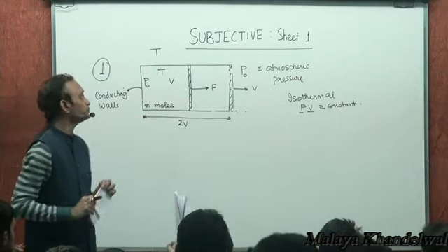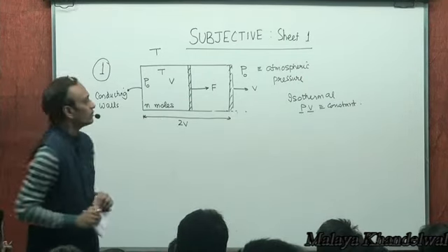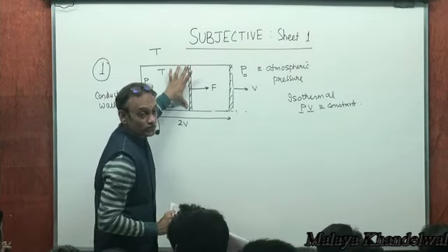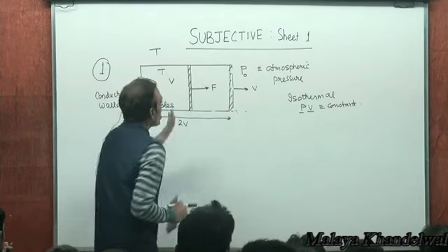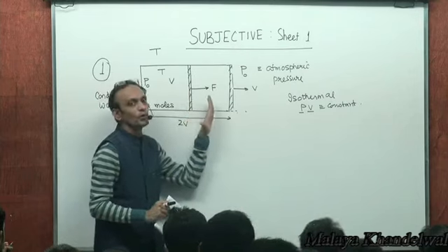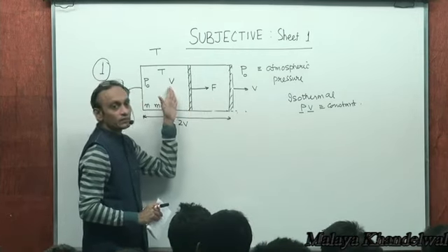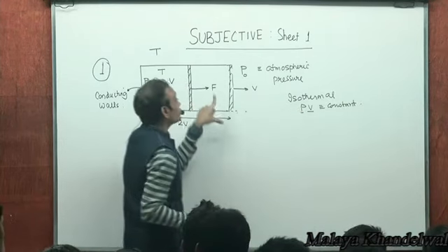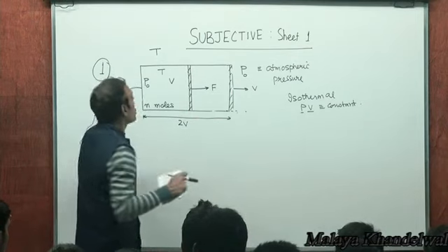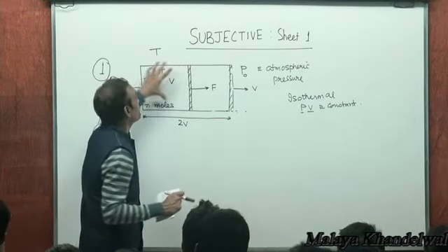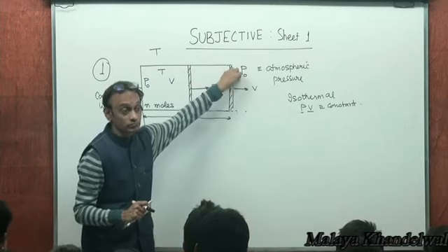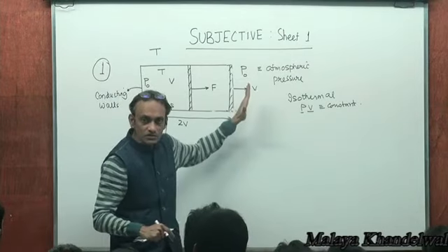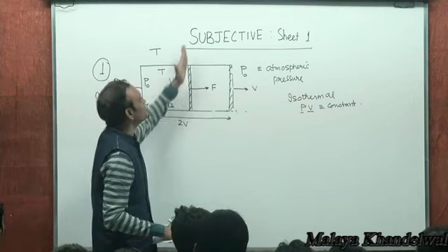Now, if you look at the free body diagram of the piston, as the piston is moving to the right, the volume is increasing, therefore the pressure in the gas is decreasing, right? Therefore the external force must slowly increase so that it maintains equilibrium between the gas contents and the atmospheric pressure. The pressure inside falls below atmospheric pressure when the volume increases, and therefore to preserve equilibrium of the piston,